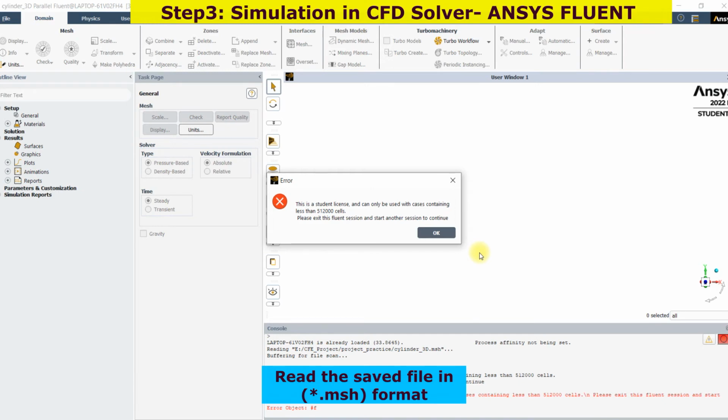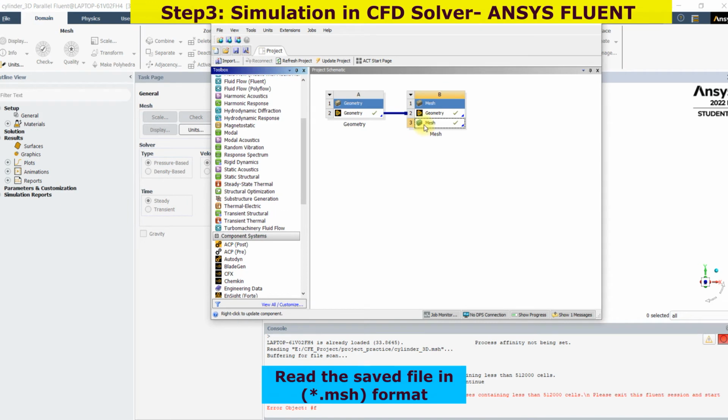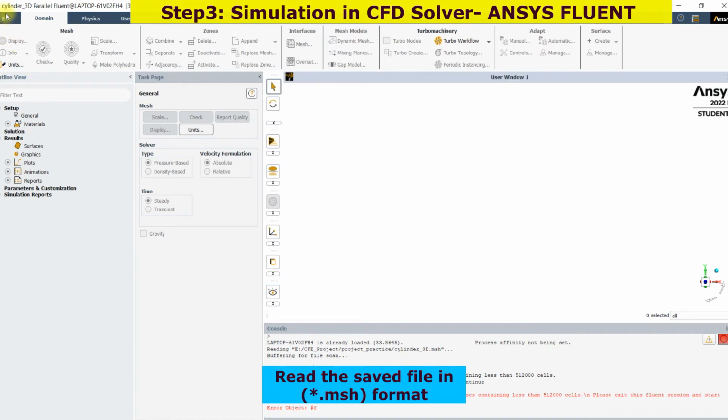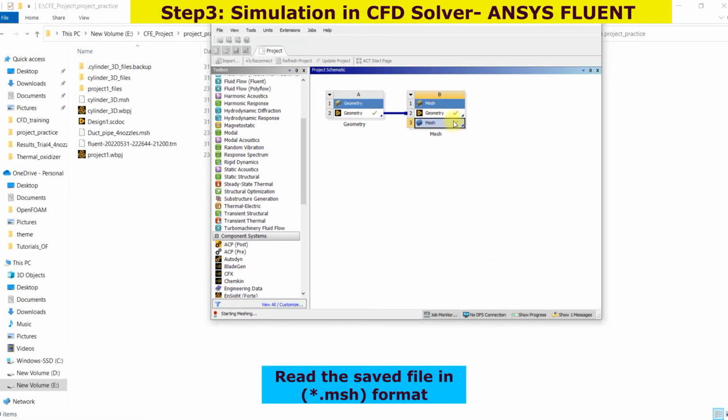Another option is we can also modify the geometry in the Z direction, because the flow is homogeneous. We can go to the geometry mode option to minimize the size. We can make the mesh coarse if we want to reduce the mesh size.